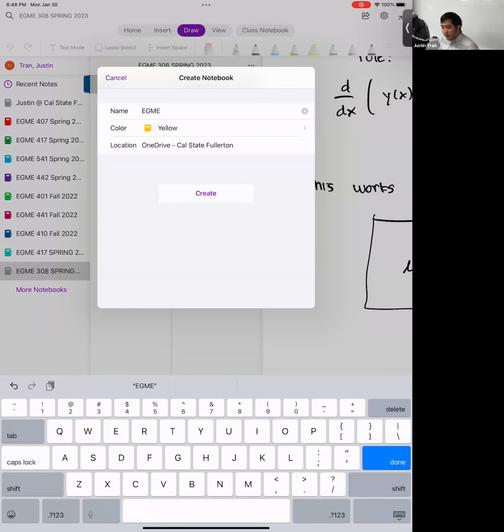Think about it. When you define the element size, you're defining this length, right? So let's pretend we have a square that's length 1. What happens if we make a square where each length is 2? Area of this one is 1, right? Area of this one, it's not 2, it's 4, right? Yeah. So when you go half the size, you don't get half and you don't get double the number of elements. You actually get closer to 4x, because it's a 2D system.